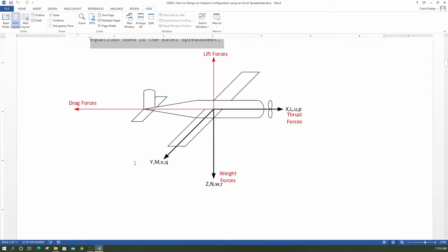So over here, it shows a nice little picture of what we're going to try to do. So this is our plane. We have an x-axis, which points with the nose of the plane, the y-axis, which goes through the right wing of the plane, and the z-axis, which points down to, say, the center of the earth. This is really the body axis of the aircraft. So anyway, what we have is this x, y, and z coordinate system. So say we have a propeller here, so we have a thrust force and a drag force along the body of the aircraft, the longitudinal part of the aircraft.